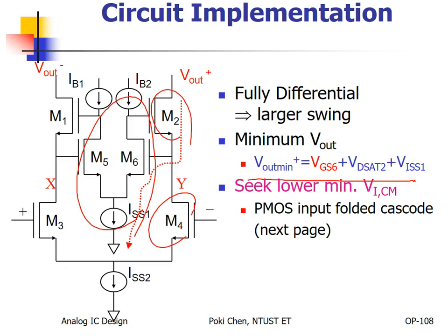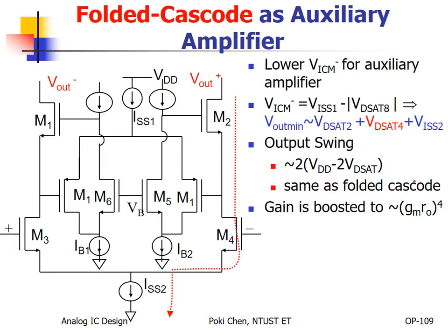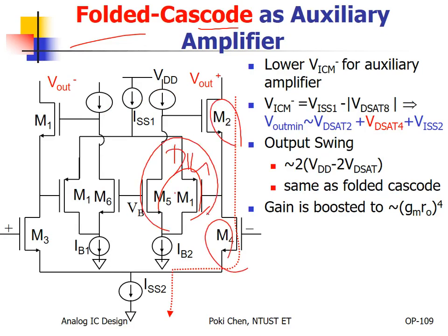So after we change it to folded cascode, you can see it is PMOS. NMOS along with PMOS. That is what we need, because with PMOS, the gate can be 1 VT lower than the drain voltage. Congratulations. No limitation with such kind of structure.